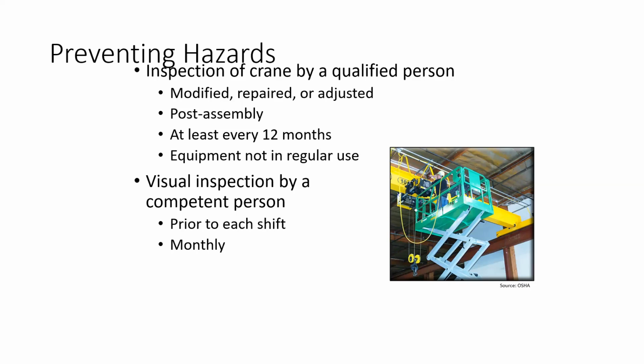If you are working with these cranes, you should make a visual inspection prior to each shift, and also monthly.